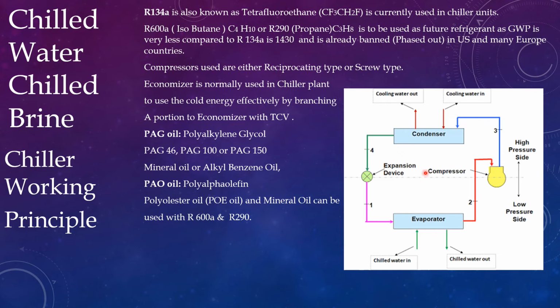One will be getting heated up, and the other will get the cooling. So the economizer is very effective. No need for any other foreign media. Only the refrigerant from the evaporator is used, which will go and get the heat, whereas the liquid freon will give up heat and get further cooling.